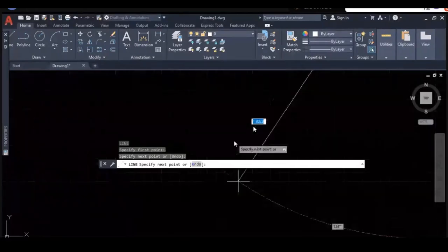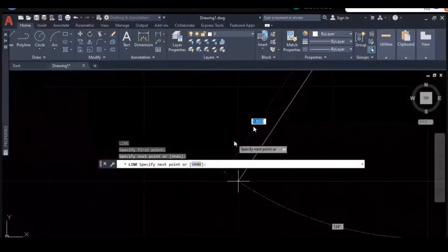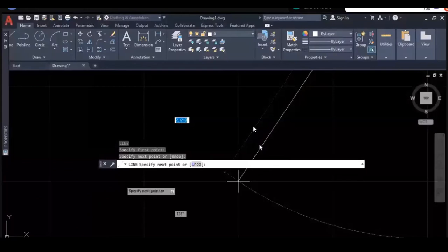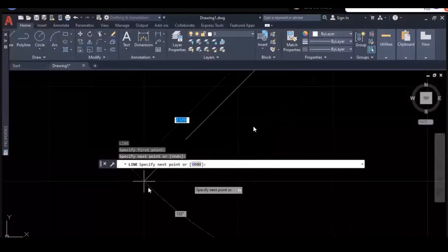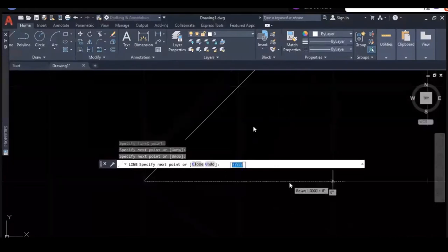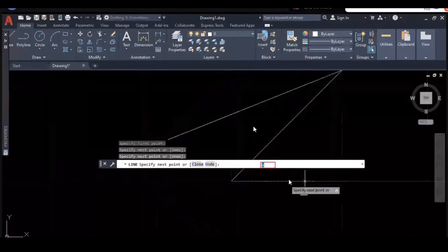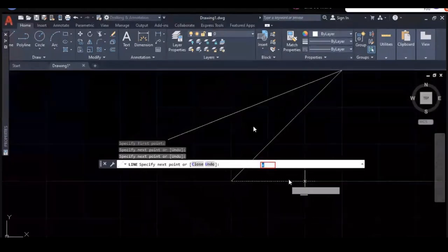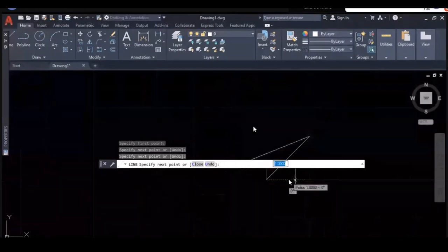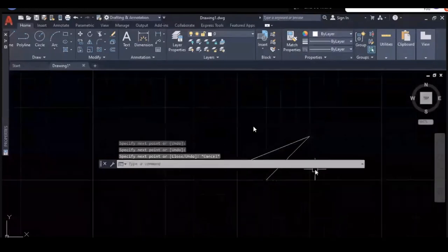The grid points are snapping points. See, this one is the grid point, where the X and Y grid lines coincide. There only you can draw. Once you turn on snap, you can't draw a line between them. If you want to draw a freehand sketch, snap must be off.